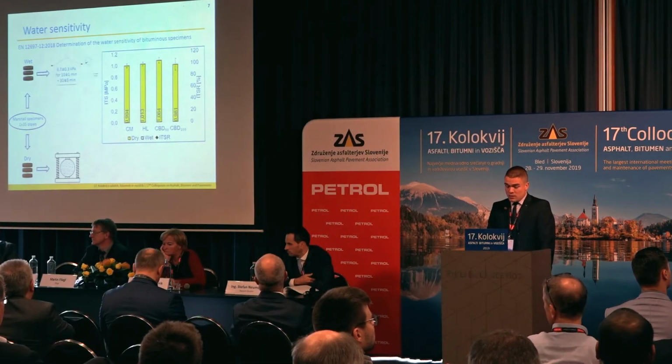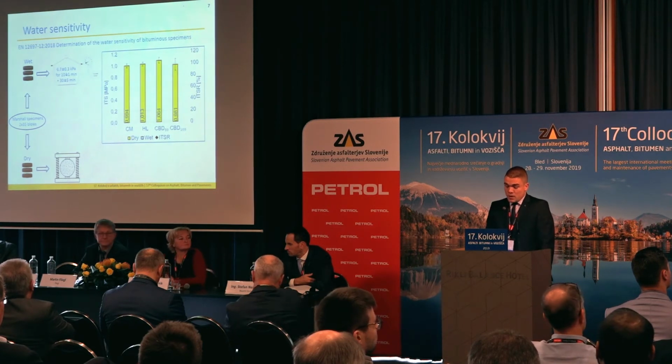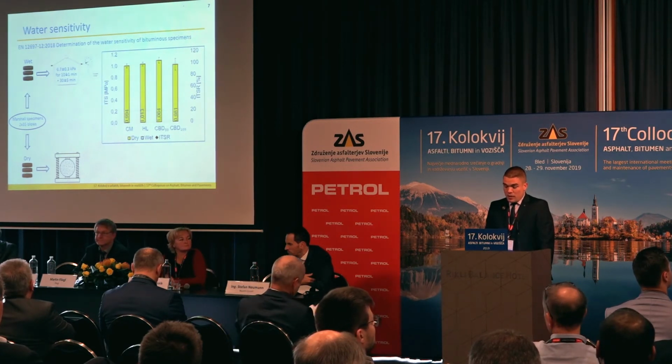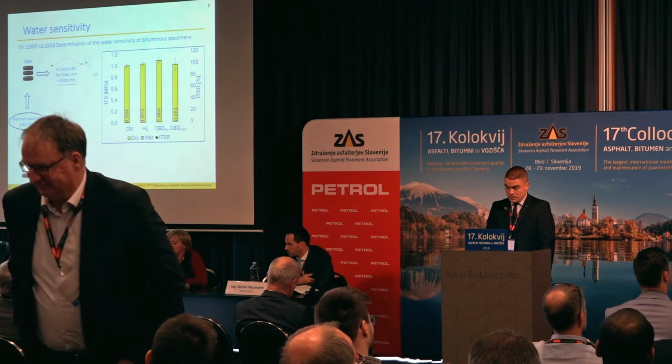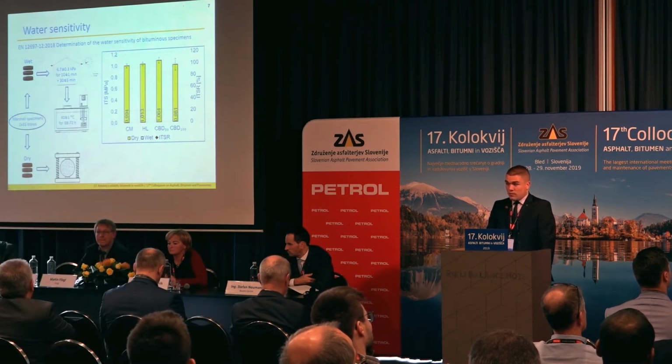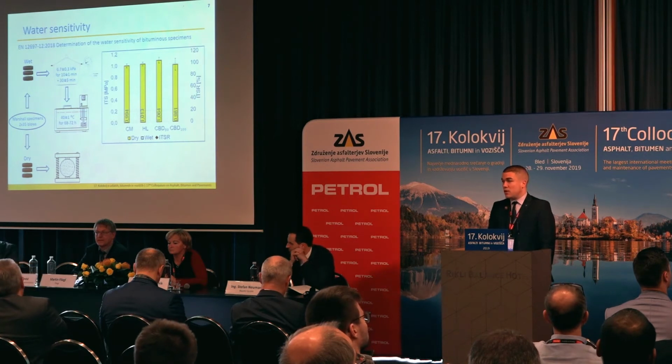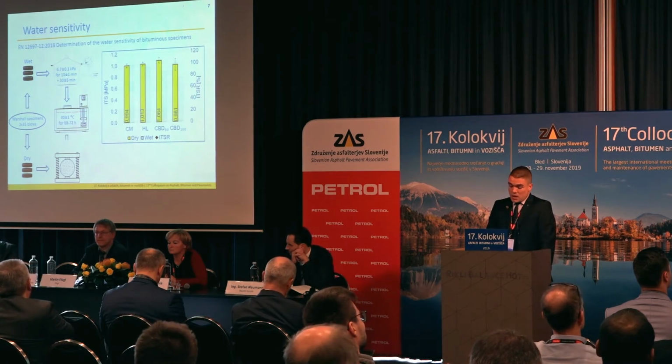The wet subset was saturated with water in a vacuum desiccator under the pressure of 6.7 kilopascals for 10 minutes plus an additional 10 minutes. In that way, saturated samples were placed in a water bath at 40 degrees for 70 hours, and